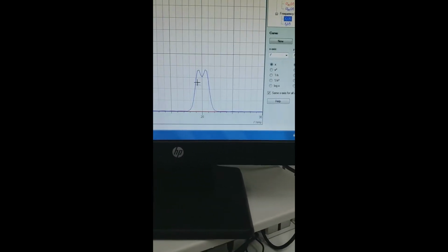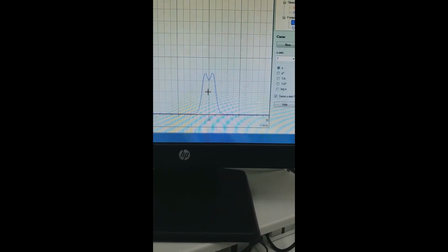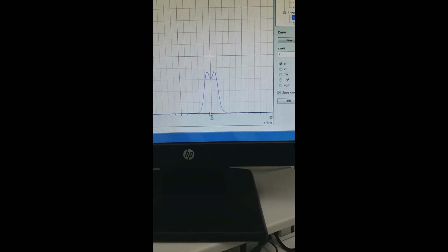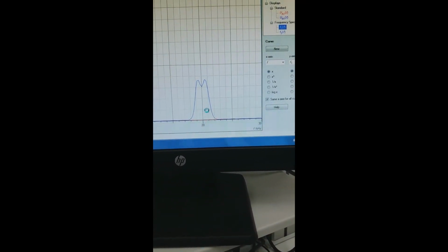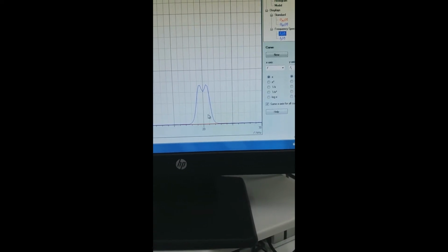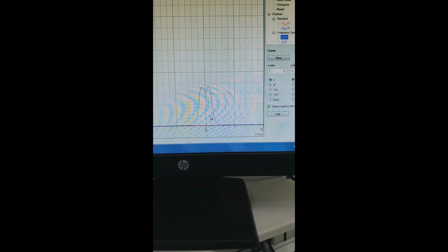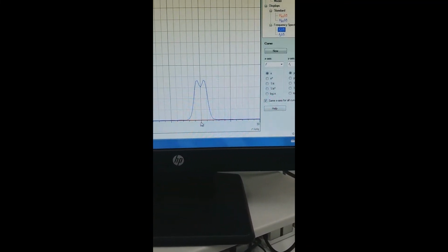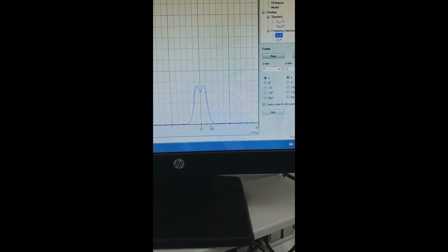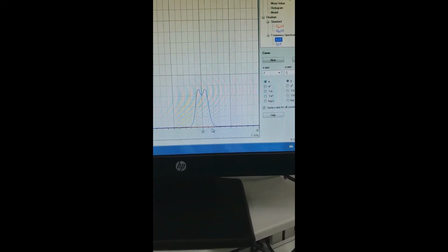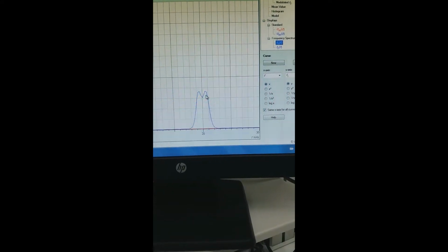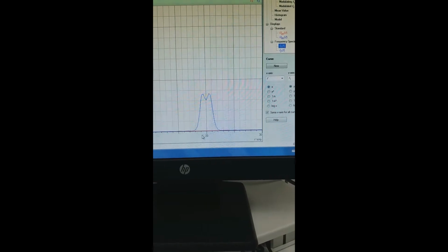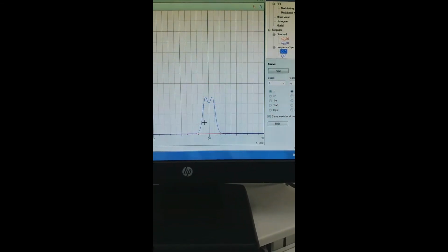Now the FM signal, the modulated signal, right? The bandwidth of FM is infinite, but here we are not seeing other peaks. The amplitude spectrum of the frequency modulated signal is centered at 20 kilohertz, with 20 plus 0.3 kilohertz, which is 300 hertz. So you are seeing peaks at 20.3 and 19.7 kilohertz, right?